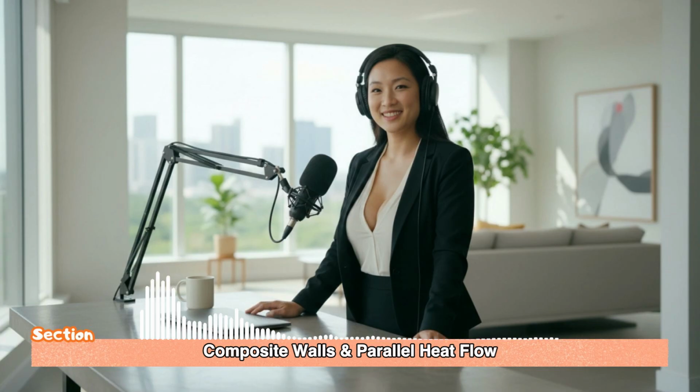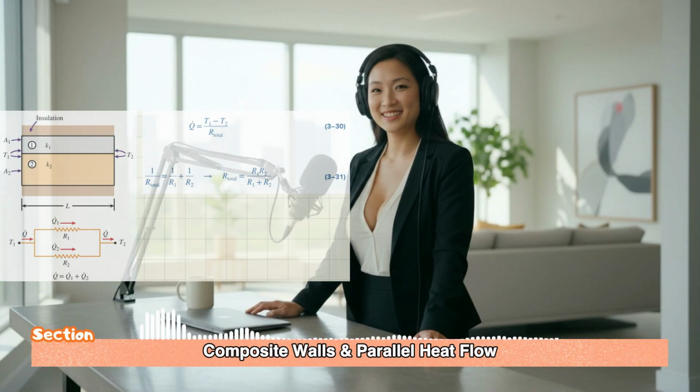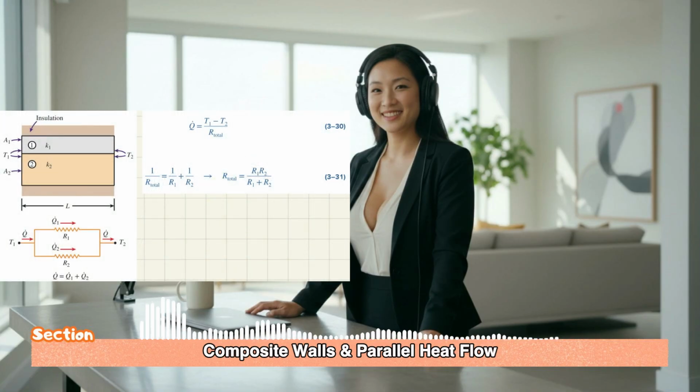It is. However, engineers still rely heavily on the thermal resistance network for approximate solutions that are usually good enough. And to do that, we have to introduce the concept of parallel heat flow. So let's consider that wall again. You have the high resistance insulation right next to the lower resistance wooden stud. They both span the same temperature difference from the inside surface to the outside surface. But the heat divides. It flows through each path independently. And that's the definition of a parallel circuit.